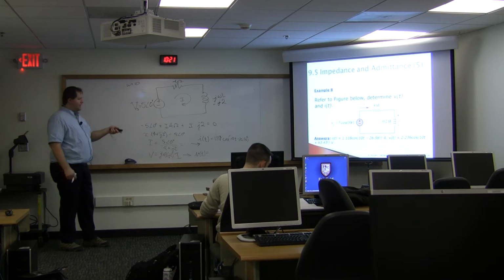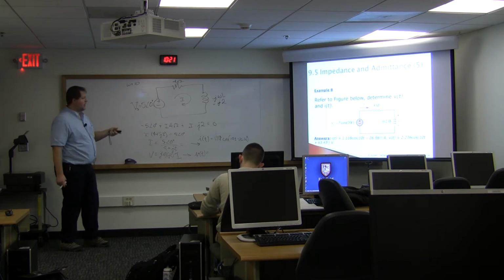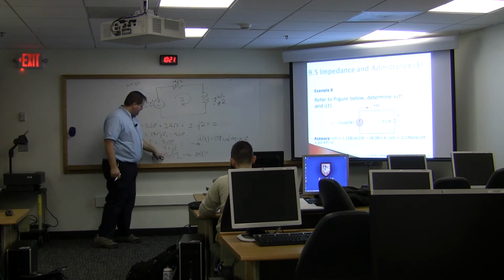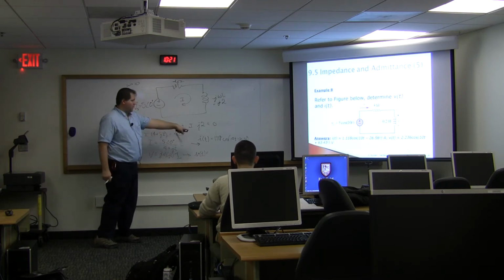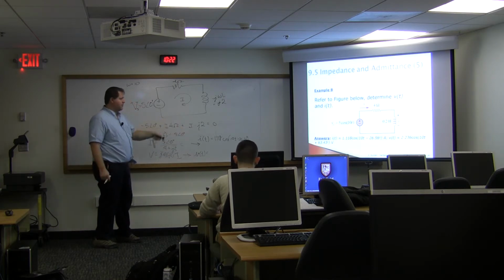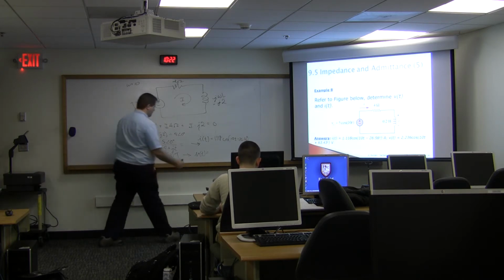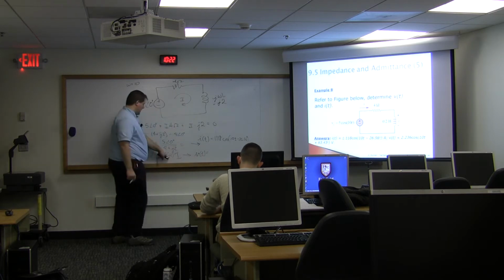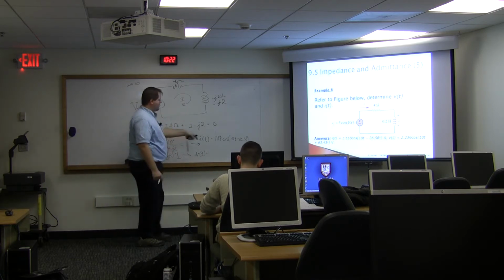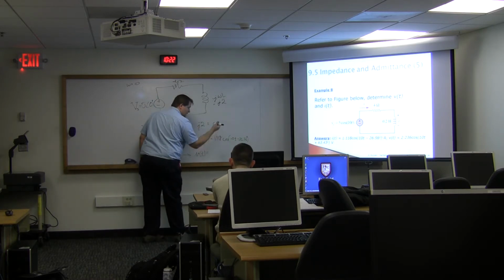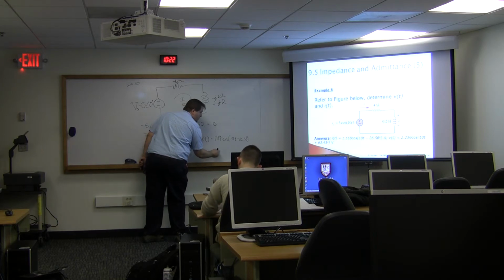And again, it works out in phasor form. I have it written down. So when we multiply, here's a 2 times 1.118, you get 2.236. The j times the j gives a negative 1. And again, you're going to be 90 degrees off on the phase here. So add 90 to the 26 and you get the 63. So that ends up with what we have on the board.